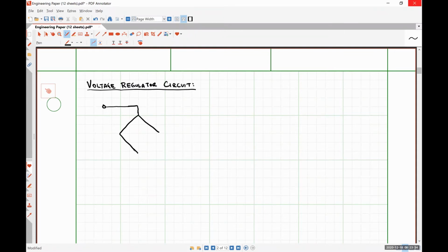And this is a symbol that Dr. Batari is using that I actually kind of like. So this big diamond with a diode in the middle of it is just representative of a diode bridge, the exact diode bridge that we use in our full wave rectifier circuits. Here's our capacitor, which is going to give us a better approximation of a DC circuit.